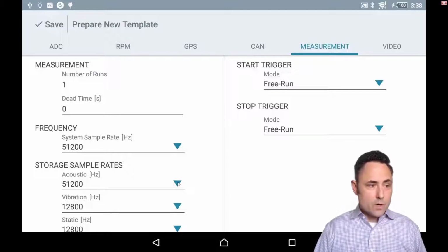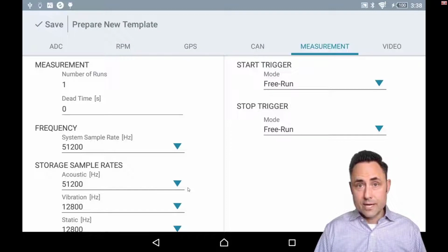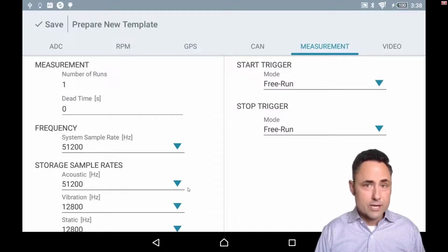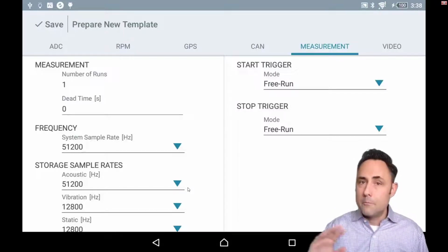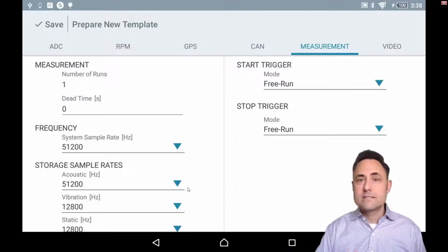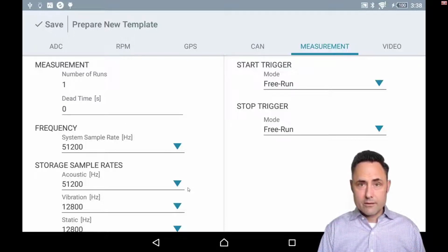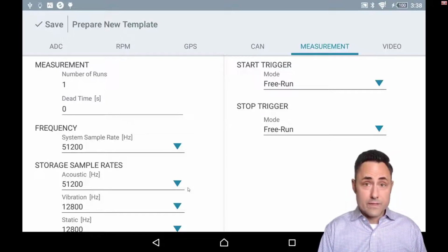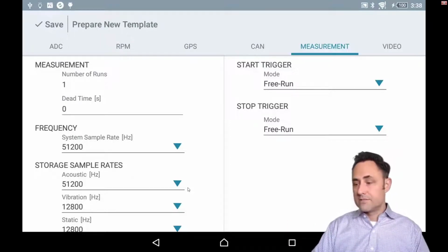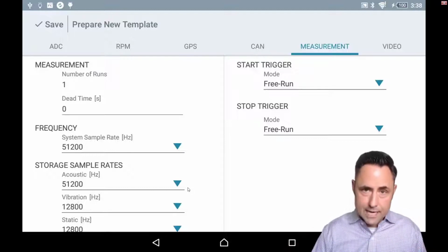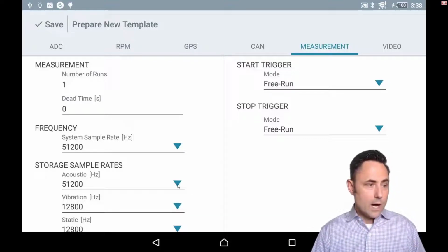In this case, I just want to also make sure that my sample rate is maxed out, right? I don't know what kind of frequency range I might be interested in, so I'm way better off sampling too fast than too slow. If I only sample at 2000 hertz, my frequency bandwidth when I go to calculate an FFT is only going to be 1,000 hertz wide, right? And so if I'm interested in acoustic information, that's going to backfire on me. And so I'm better off setting up this generic time acquisition as being wide open.